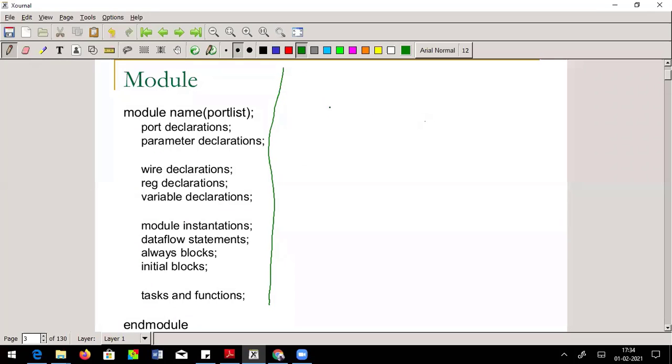Right. So now let's see the way to write code. Now you know what a keyword is. You have a list of keywords which are used for a particular purpose. You are not supposed to use those keywords for anything else, like giving names. So the keywords are module, and once you write a module, it also comes with endmodule. It's something like a main program.